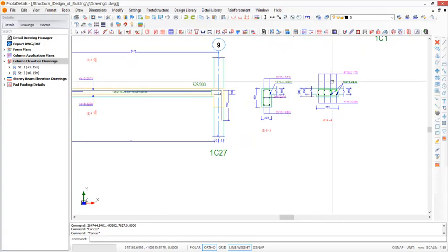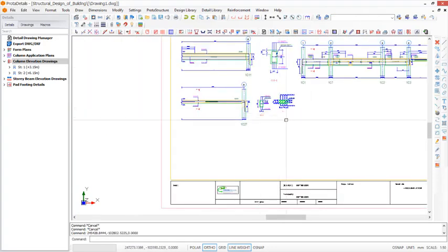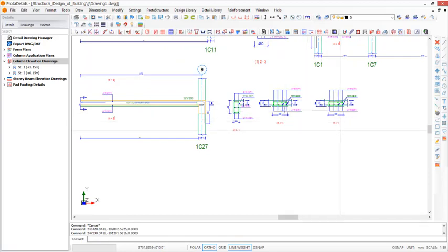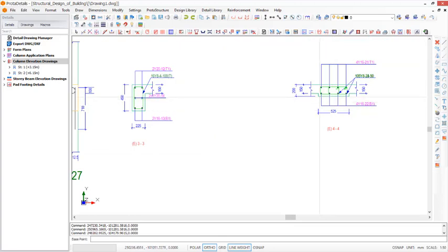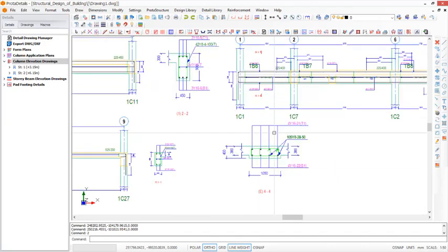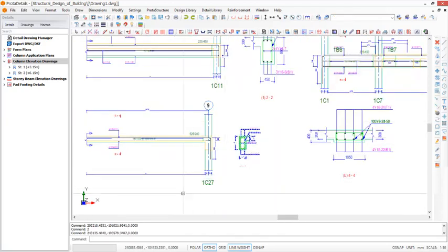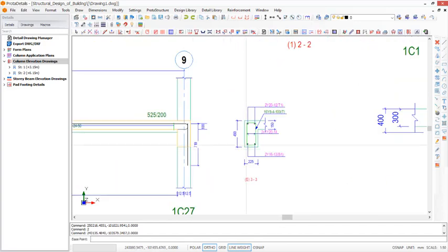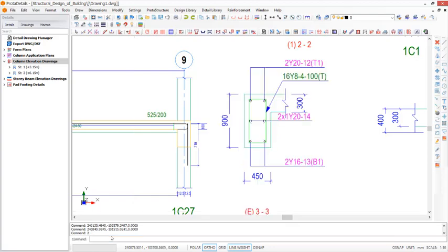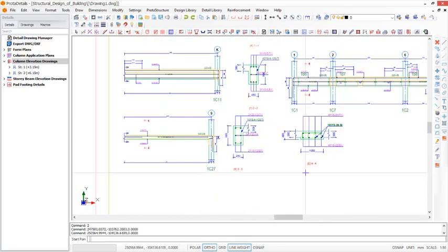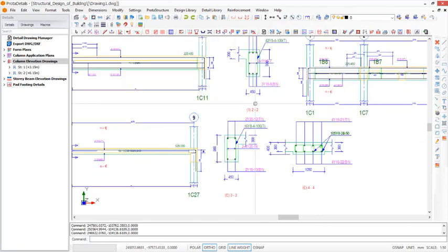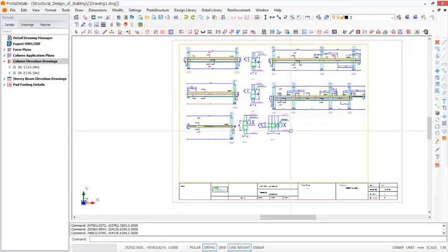Okay, for this you can as well give this some scales to make it bigger. So you have to key in scale, enter on the keyboard, pick base point, come over here to right there, enter. Just like this. Same thing applicable here. To scale, enter on the keyboard, pick this point right here in the scale bar, 2, and enter, just like this. Then you can move it closer a little bit so as not to occupy much space right here. So just like this, you can have this being arranged like this.